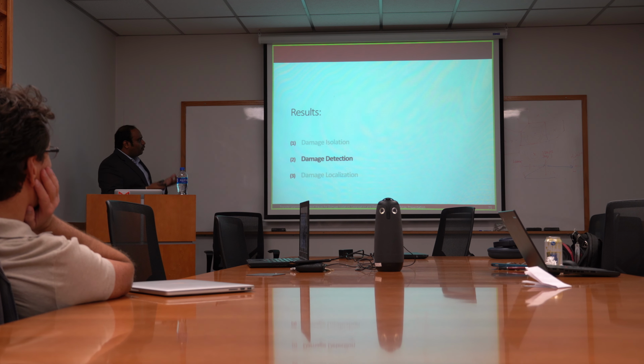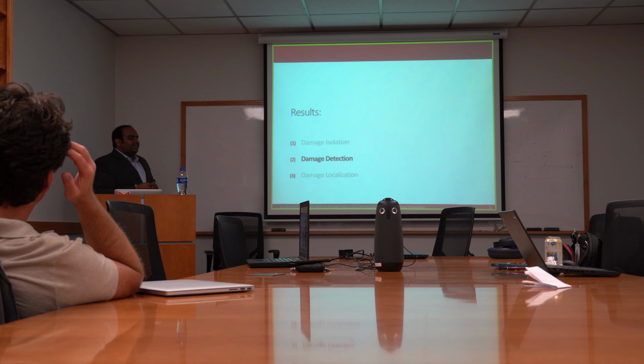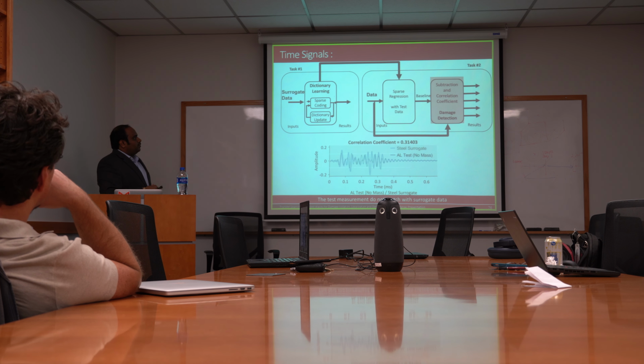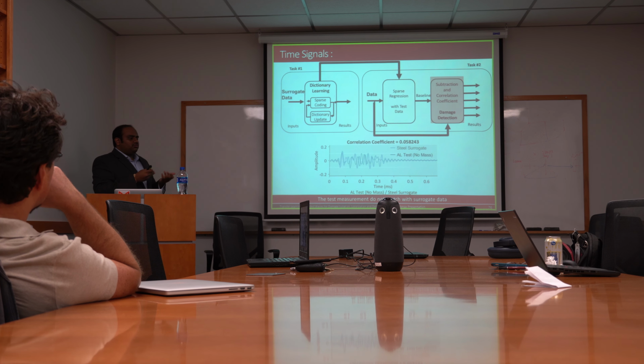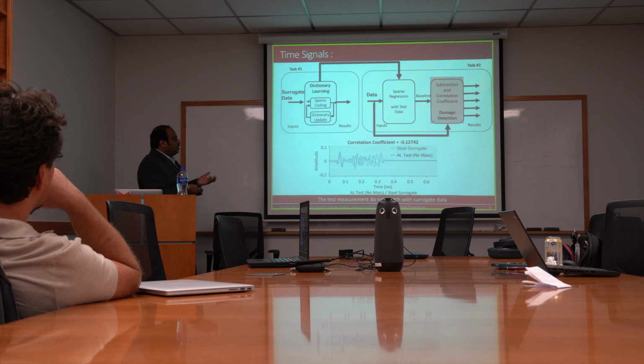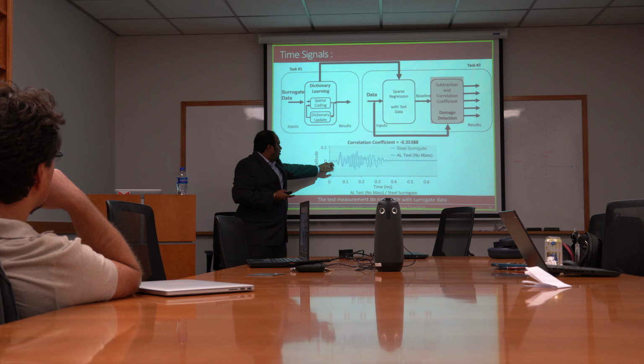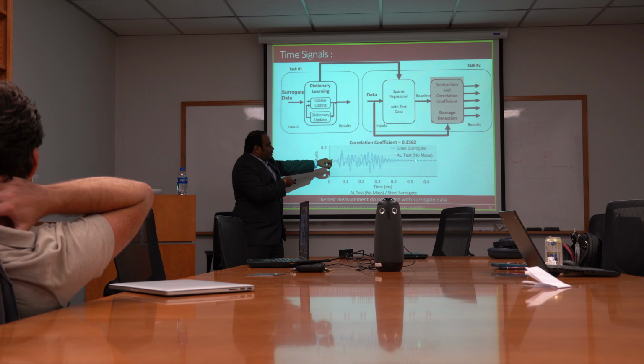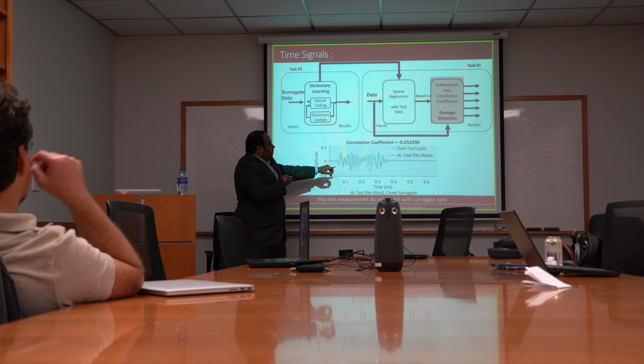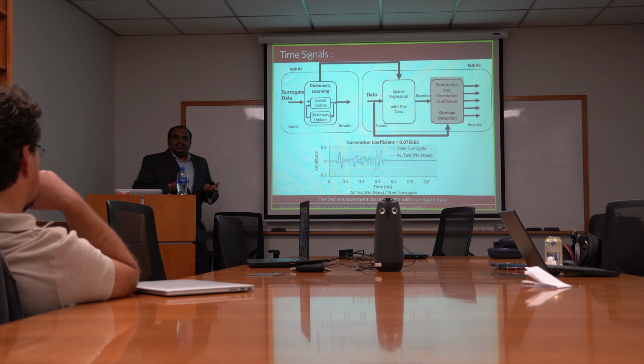So what else can I do? We can also do damage detection. So instead of measuring every point on the structure, now I only take 5 to 30 or 50 different measurements. And what I do is I compare it with the steel structure. Now I have an aluminum plate with no mass in it and a steel structure. As you can see, the correlation is very bad. All I wanted to say in that is I am using a very dissimilar data to do the transfer learning.